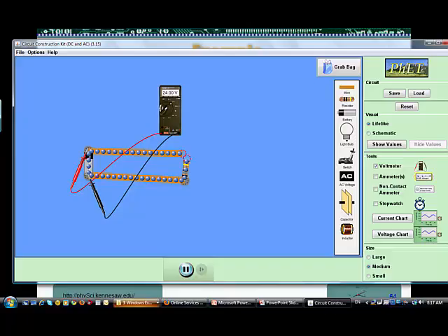So whenever it's in an open circuit, whenever the battery is not delivering current to the circuit, the voltage drop across the battery is the ideal voltage drop, the voltage drop that's given by an ideal battery. The minute it is part of a circuit, there will be a voltage drop across the internal resistance of the battery, so that to the outside what we see is not going to be the full 24 volts, but like in this case 21.48.